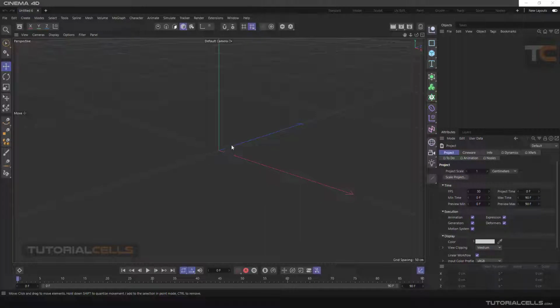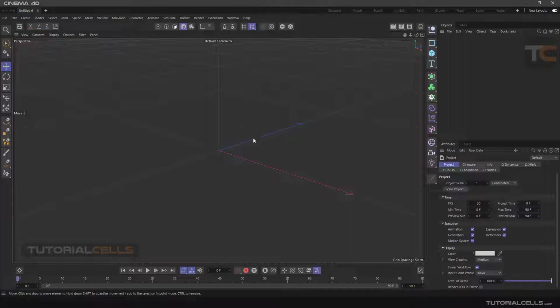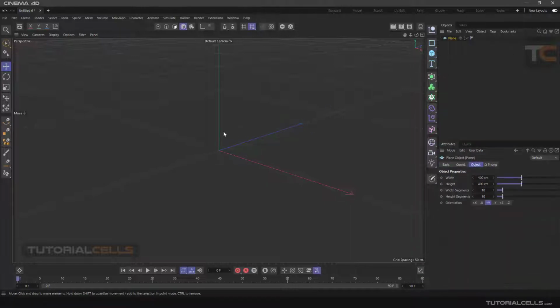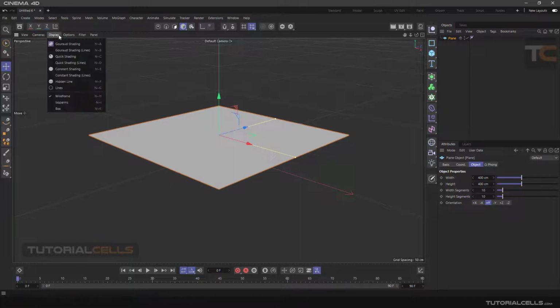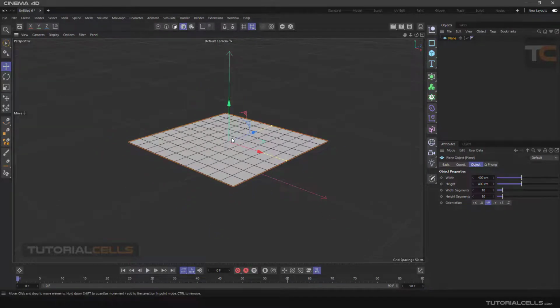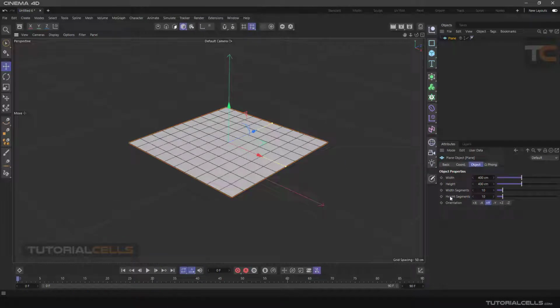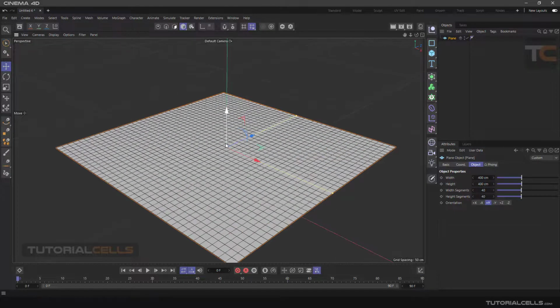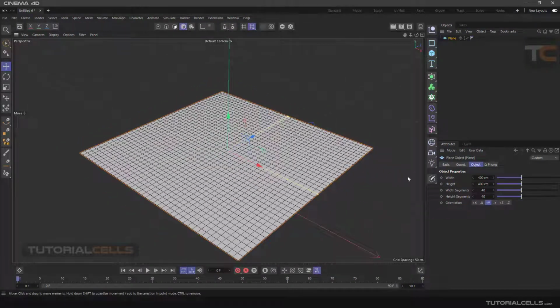In this lesson, we want to explain soft selection mode in selecting elements of the object. To do this, we insert a plane in a detail section of the viewport. Select the ground shading line to show the lines of the parametric object. We increase the number of the lines a bit from the object setting in a segment section for having more polygons or point or edges elements when we convert the parametric object to an editable one.